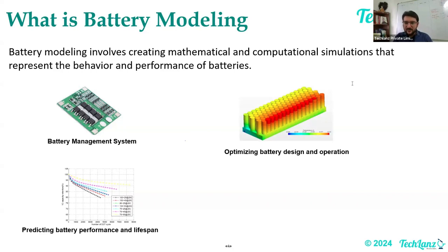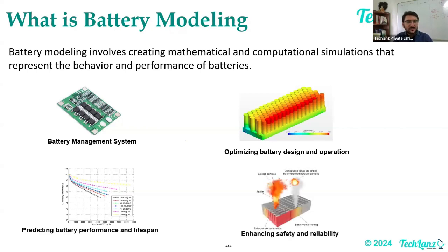Yeah, battery models act as a digital twin, as Rishikesh mentioned, letting us understand and optimize battery performance, safety, and lifespan, right? Let's talk about the safety aspects also. So, yes, especially from the safety perspective, people model the complete thermal runaway events also. This is a very important slide to understand that each of these applications is very different. A single model cannot be used for all these applications.